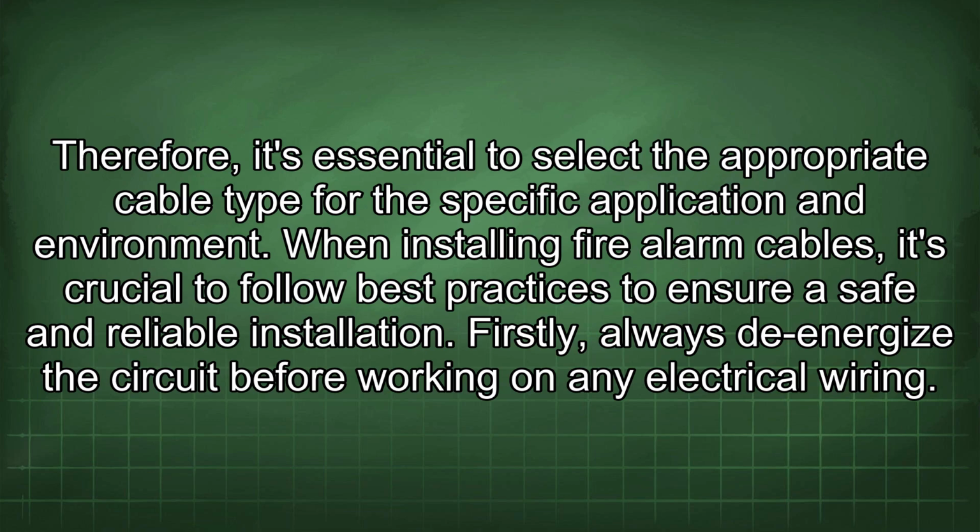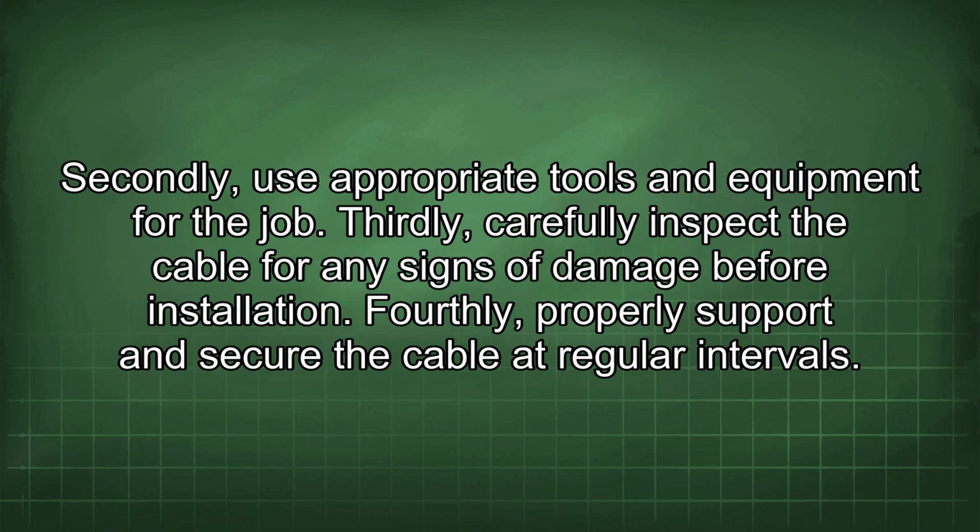When installing fire alarm cables, it's crucial to follow best practices to ensure a safe and reliable installation. Firstly, always de-energize the circuit before working on any electrical wiring. Secondly, use appropriate tools and equipment for the job. Thirdly, carefully inspect the cable for any signs of damage before installation. Fourthly, properly support and secure the cable at regular intervals.